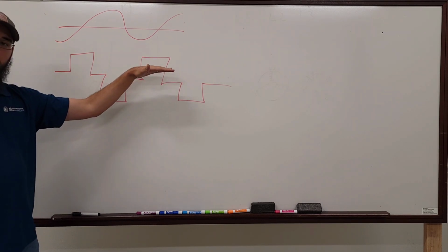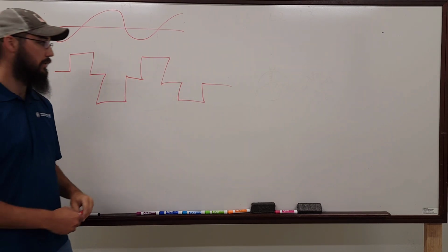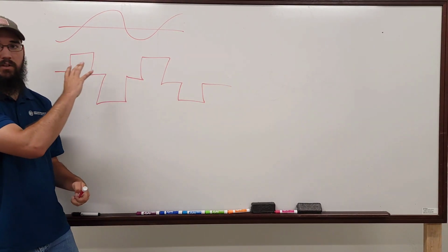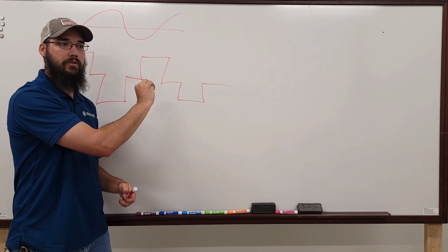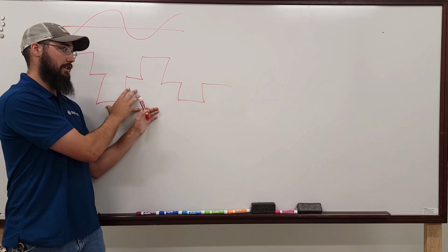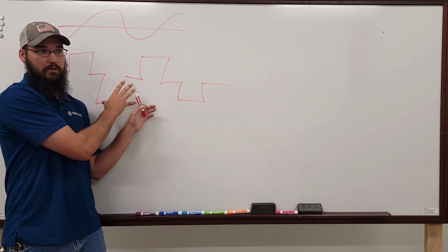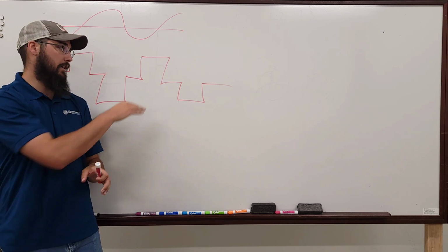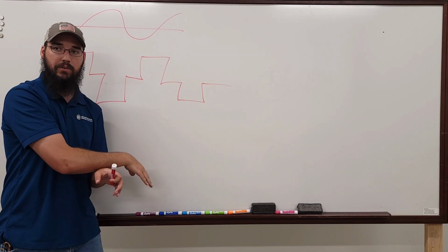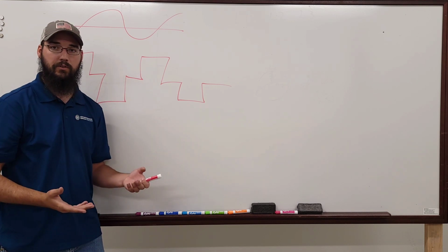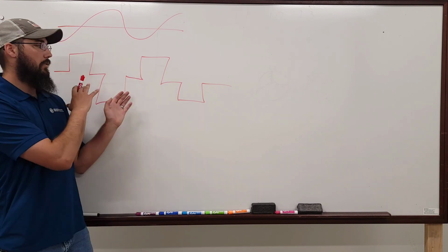This sine wave is artificial in its creation, right? This is actually DC voltage being simulated into an AC sine wave via positive and negative pulses on gate modules, which we call inverters. It's built into the VFD.